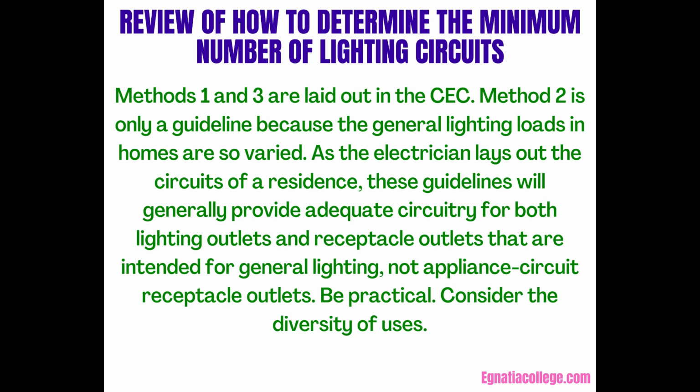As the electrician lays out the circuits of a residence, these guidelines will generally provide adequate circuitry for both lighting outlets and receptacle outlets that are intended for general lighting, not appliance circuit receptacle outlets. Be practical. Consider the diversity of uses.